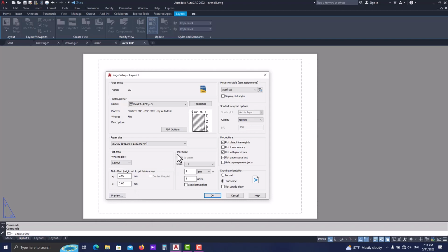And in this side, we have another important thing to set, which is our scale. Now, if you remember our previous session, we said that the first thing that we need to do is to change this from inch to millimeters. For example, to use the scale 100th, we needed to put this on 1000 millimeters, then put this one on 100.